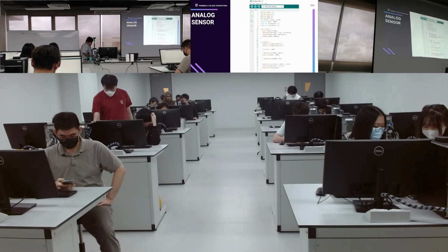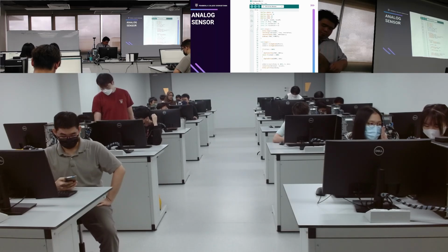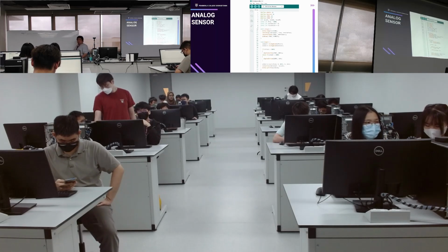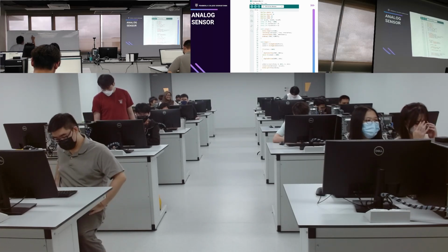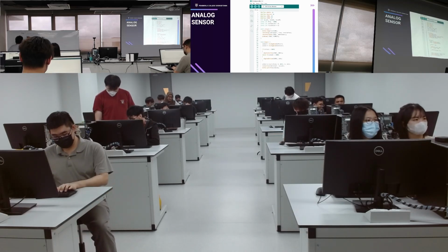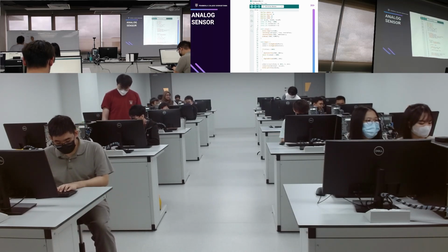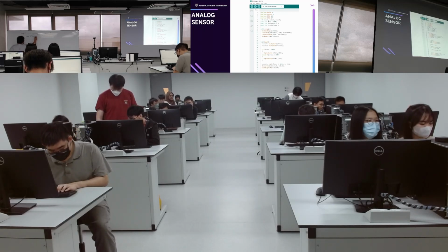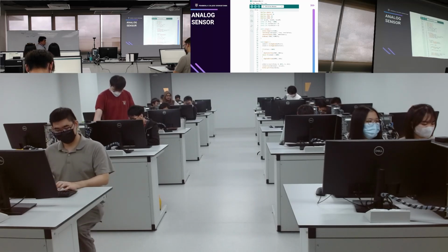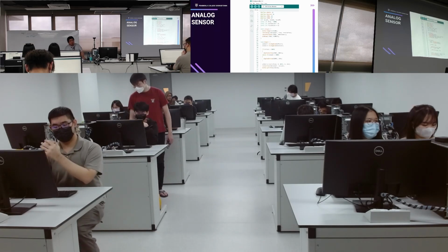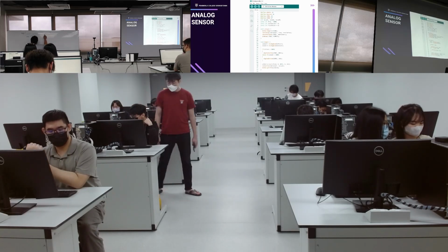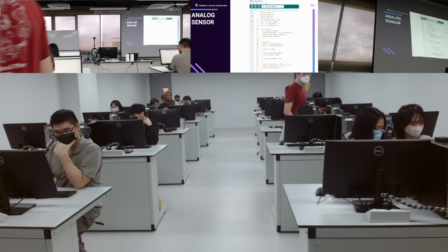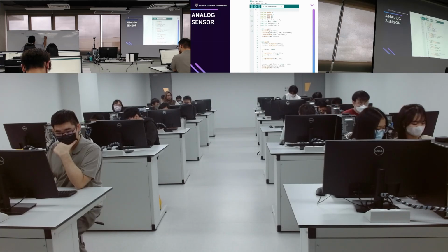If we want to use map, we have 4 values. The first 2 values are the range of input. Then the other 2 values are the range of output.